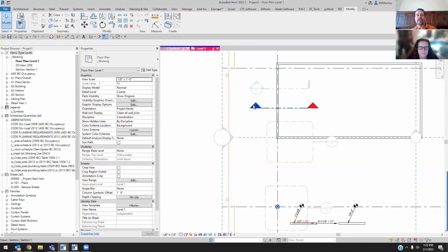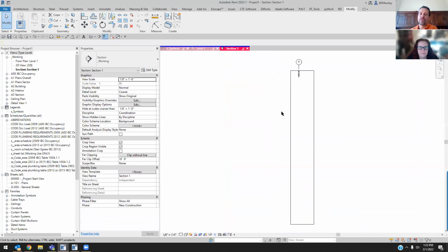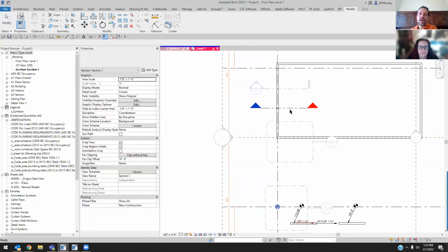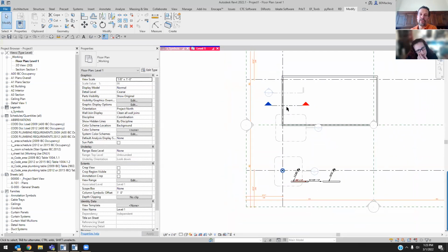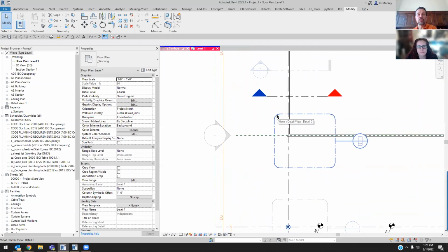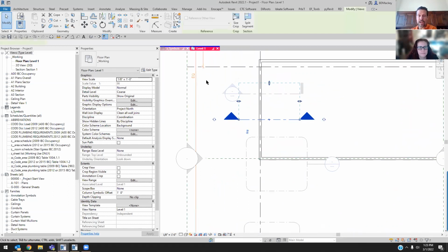The reason this side is blue is just because that's the hyperlink you can double click on. So that's why this is red and blue. I also have filters to change them all to different colors in different views. So if I go to printing views, they're usually turned off, but if somebody turns them on, I override the whole thing to be red, kind of like these ones are all half toned. I use a lot of filters for that stuff, but yeah, this is my working section heads. This is what they look like. I know these shouldn't ever belong on a sheet, so we're good to go.